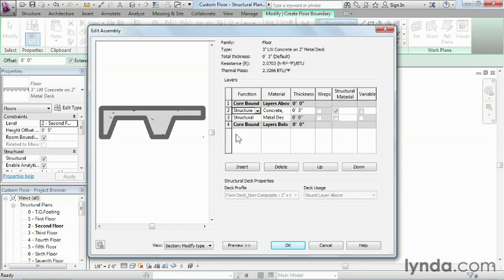Now, back specifically talking about floors, if we wanted this to be back to just being a 5-inch thick floor, we just type in 5 inches here. We'll need to click somewhere out in space in order to be able to make this actually get its thickness back again.